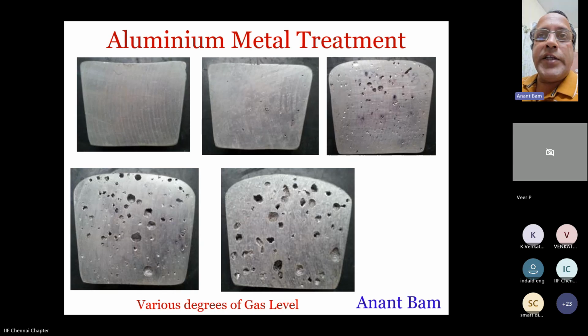We are taking another sample in ambient air, which is not under vacuum. So it solidifies naturally and it represents its natural density. So the difference between the density of air sample and the density of vacuum sample, expressed as percentage of density of air sample, is density index. It is expressed in percentage.